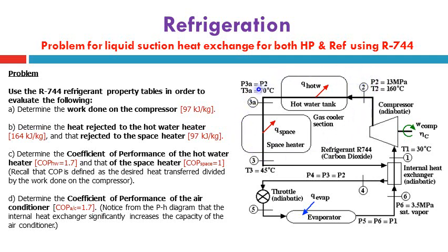There is no condensation process, but it is a heat removal process, and in these gas cooler sections we can use this gas cooling to increase the hot water temperature and also to condition a certain space. That is the main concern for using CO2 in some heat pump systems, acting as a heat addition system to water or to space.